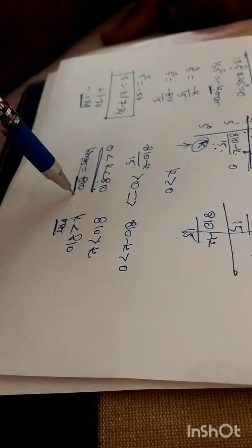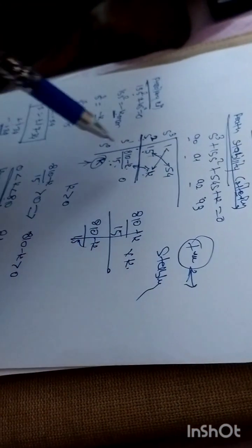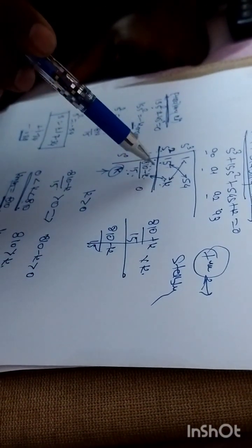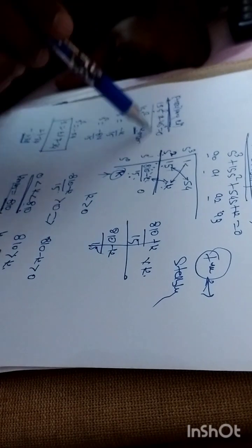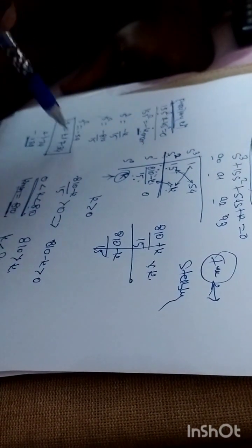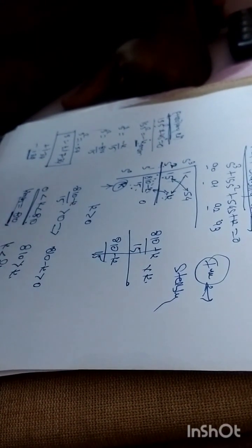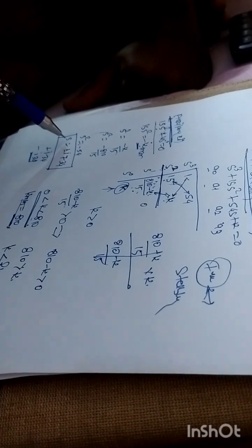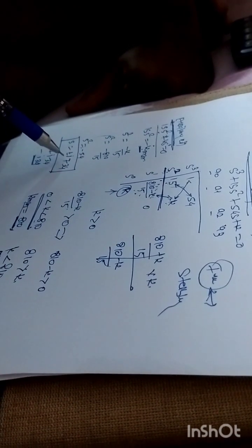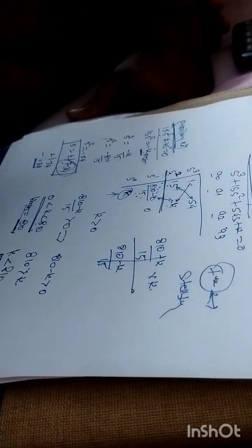To decide the intersection on this imaginary axis, we consider the auxiliary equation from this root locus array. So the auxiliary equation is 15 s square plus k into s raised to 0, right? By taking this marginal value of k as 810, the intersection on this imaginary axis will be the 2 points plus minus j 7.34. So these are the design steps.